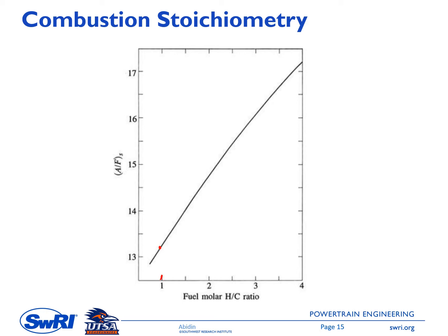An example of a fuel with Y equal to 1 is benzene. And on the highest one here, we have HC ratio equal to 4, and the stoichiometric air-fuel ratio is slightly above 17. An example of HC ratio equal to 4 is methane. So you have Y equal to 4 here.